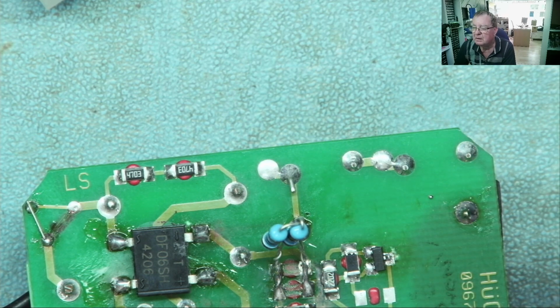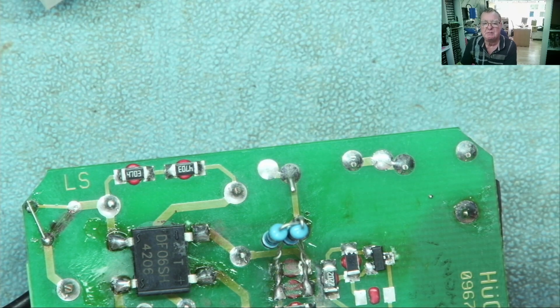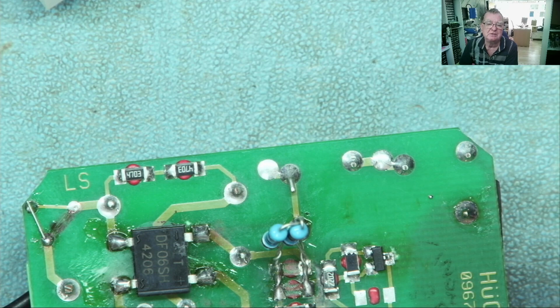So that's commonplace. The other one, but this will only apply if you're working on vintage equipment with vacuum tubes or valves. Those circuits have a lot of fairly high wattage, often high value resistors into the hundreds of kilohms or megohms. And again, with age, they just tend to gradually increase in value to a point where the circuit no longer functions. So in that case, high value resistors, they have a habit of just failing.